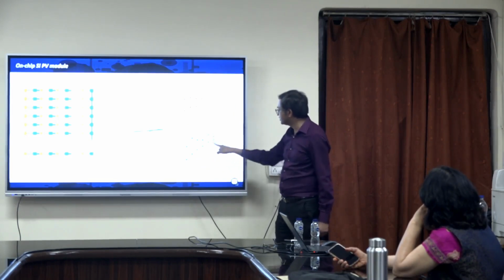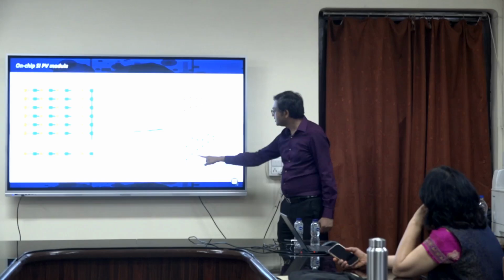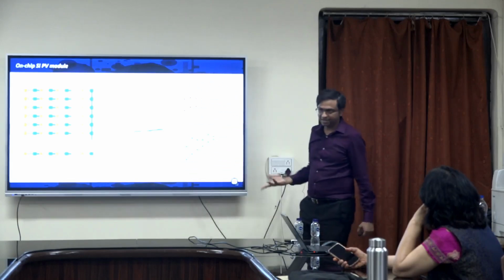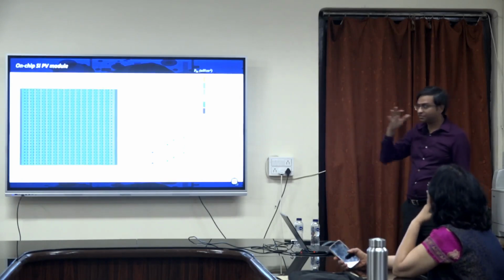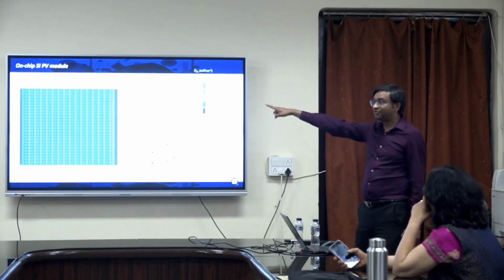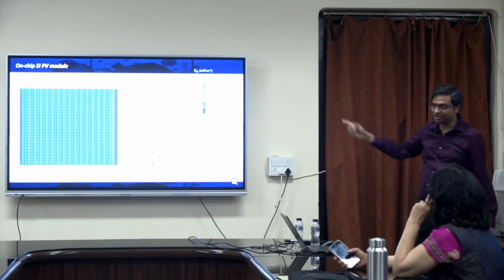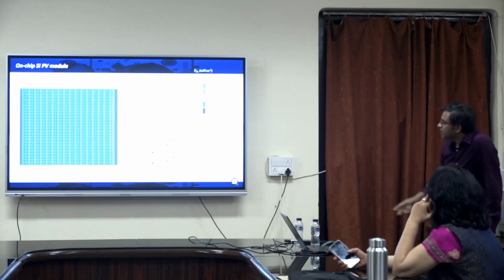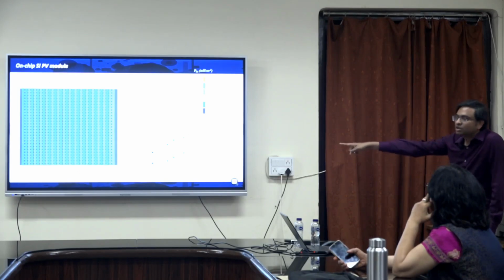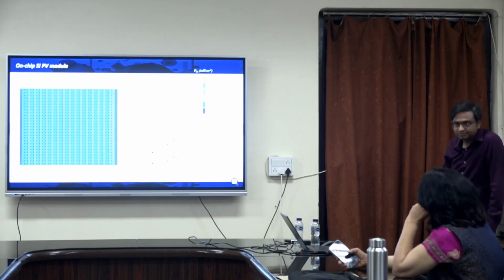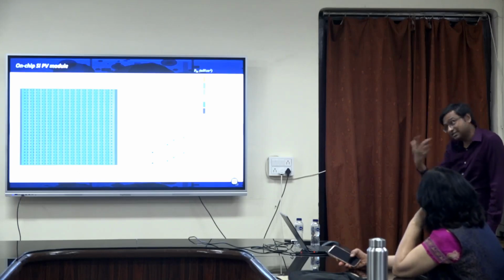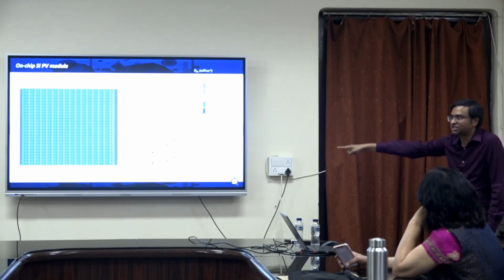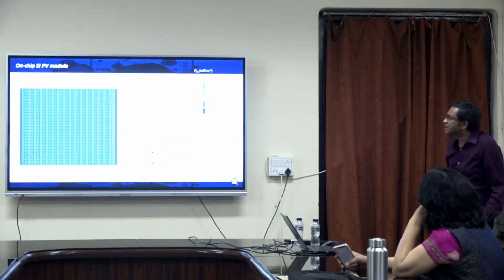While the current increases, you see this curve, as I get to more number of parallel connections. And eventually, for this entire array that we have done, which is having a 16 cross 100, 1600 that many devices are there, we ultimately get to 2.8 microwatt. With that, now my next objective is to make my devices low power, right. If the devices are very high power, then I will not be able to use only this much power to run everything, right. So that is what we do.